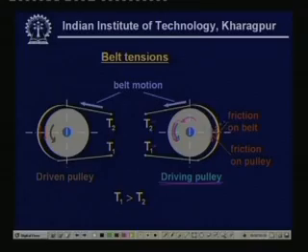This friction onto the pulley will be in such a way that it will try to oppose the motion of the pulley. So, it will be in this direction. Thereby the friction on the belt will be in the other direction, opposite to this particular direction. So, you can see that this particular friction onto the belt will do what?